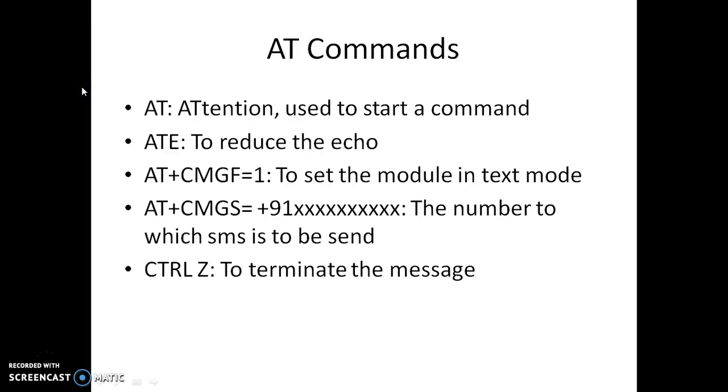In order to communicate between the GSM and the 8051, there are AT commands. So here is the list of AT commands. First one is AT. AT stands for attention. If we give the AT command, it will respond with OK. Then the second is ATE0. ATE0 is used to reduce the echo. Then the next one is AT+CMGF=1.